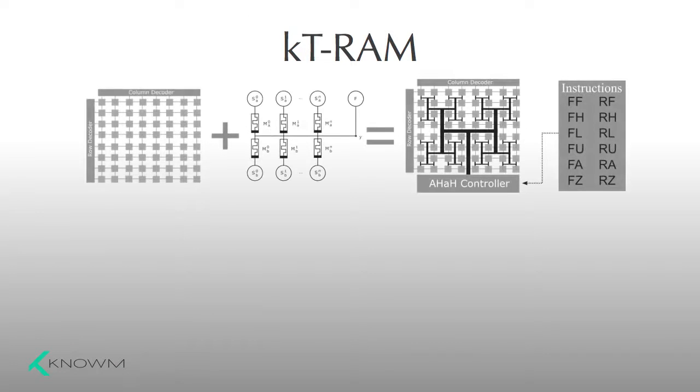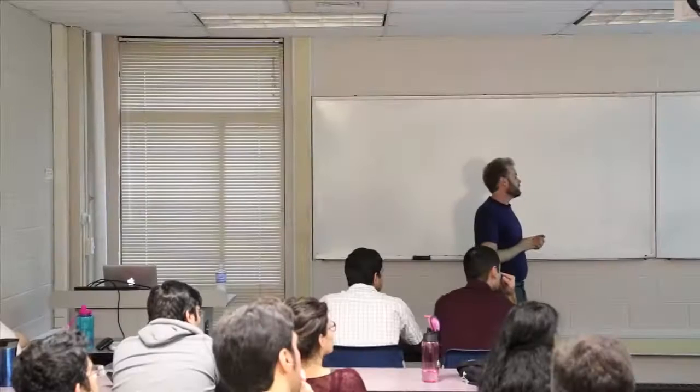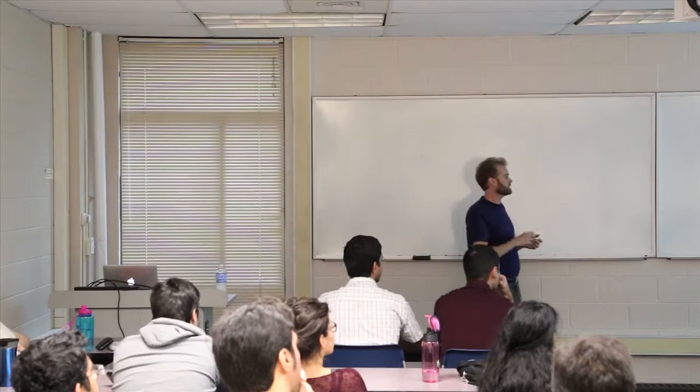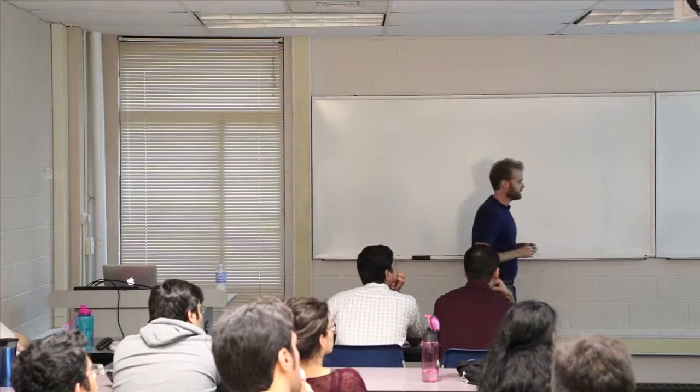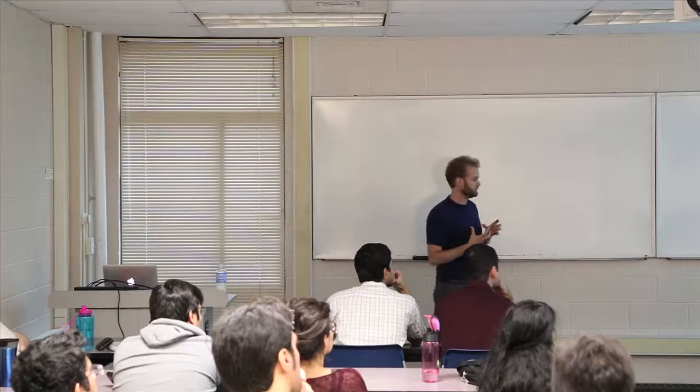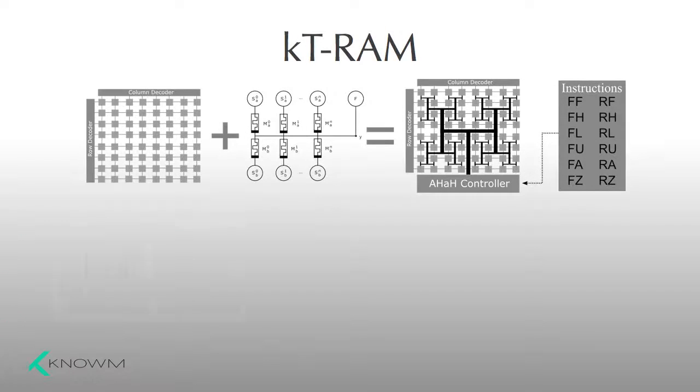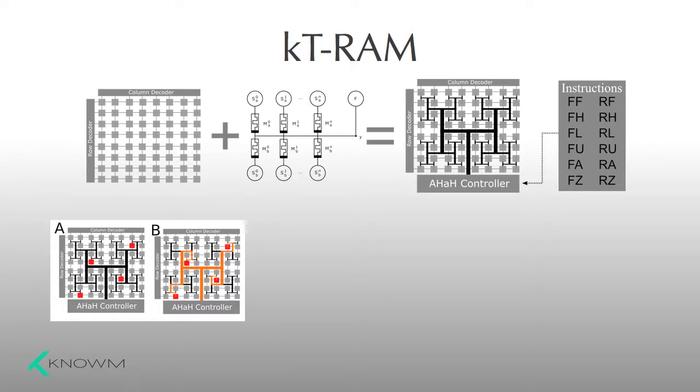Okay, so now we have a bunch of these synapses, you can see here, and we can start to array them together. And you can think of this as a neuron. Every one of those differential pairs would be like a synapse, and that common node that connects them all together would be like the neuron, a neuron being a collection of synapses. But we can do something pretty tricky, which is we can couple it to random access memory in such a way that we can selectively couple synapses together. To give you an example, we can turn on, say, these synapses here. And by doing that, we're coupling them all together to a common electrode. All the other synapses are decoupled. And then we can drive a voltage across them, and only those, and allow them to interact according to anti-Hebbian and Hebbian plasticity.